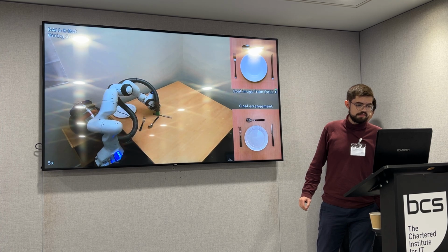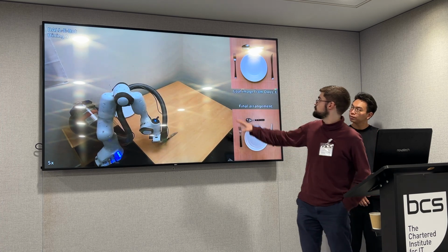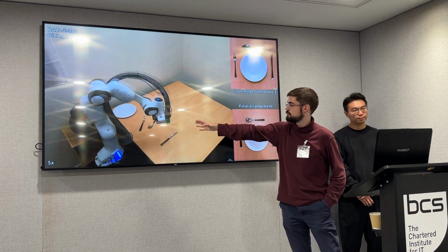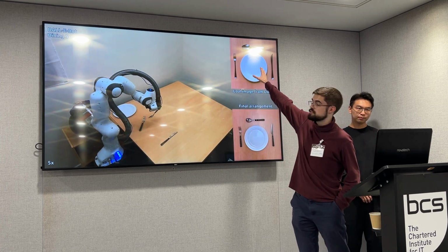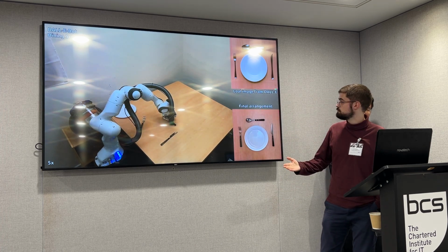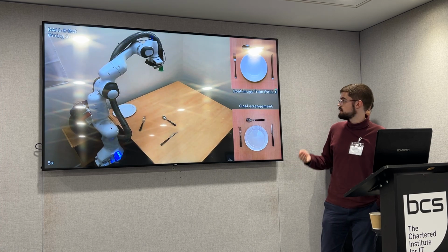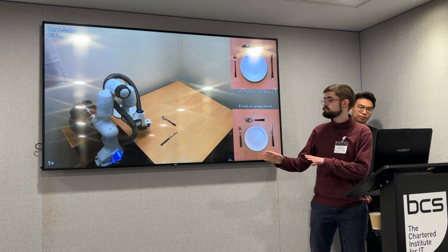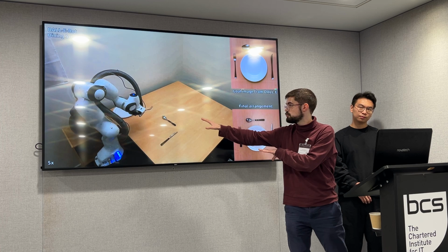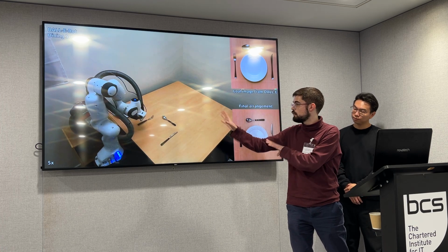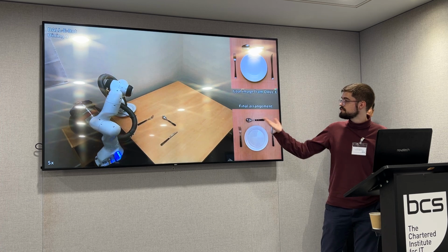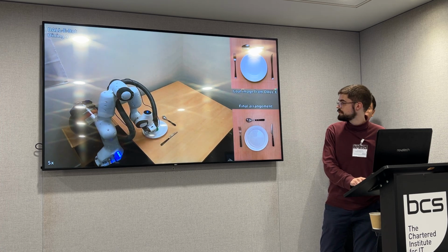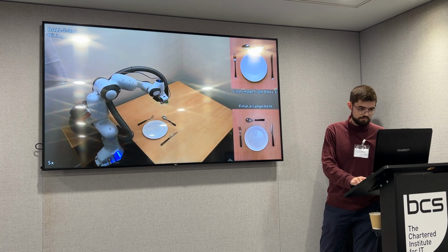And you can see basically what it needs to do is match between the generated image and the initial state of the real world. It needs to figure out by how much to move each of the real objects to match this arrangement. And then we use motion planning to perform this pick and place and put the objects into their goal poses. And notice we don't need to do any training. This is fully zero shot. We just use this web-scale visual prior to figure out what a good goal state should be. And the method is fully autonomous as well. So we don't need any human demonstrations or human effort.